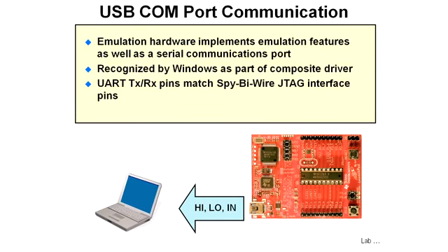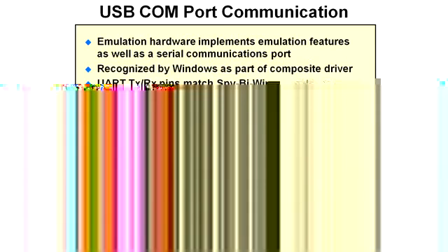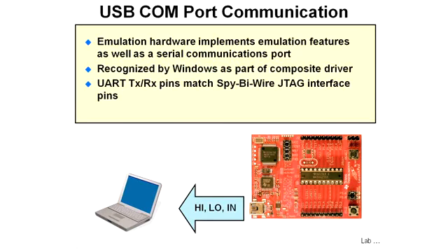The COM port communication on the LaunchPad board is set up in basically 2 ways. If you're doing a software UART, the pins that you talk out of are connected to the emulation port that will end up at the USB interface. You could connect directly to those pins and use those as your UART connections. And if you take a look down on the board, you can see that port 1 pin 1 and port 1 pin 2 are both connected as the UART.